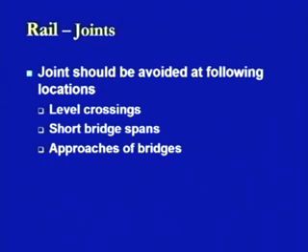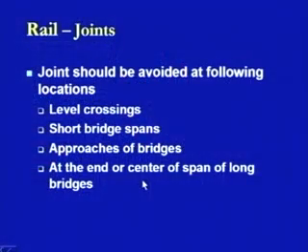Those are the smaller bridges, whereas in the case of the approaches of bridges, again for similar reasons of induced stresses, we try to avoid joints. Then there is another location, the end or center of the span of long bridges, where again the joints should be avoided.